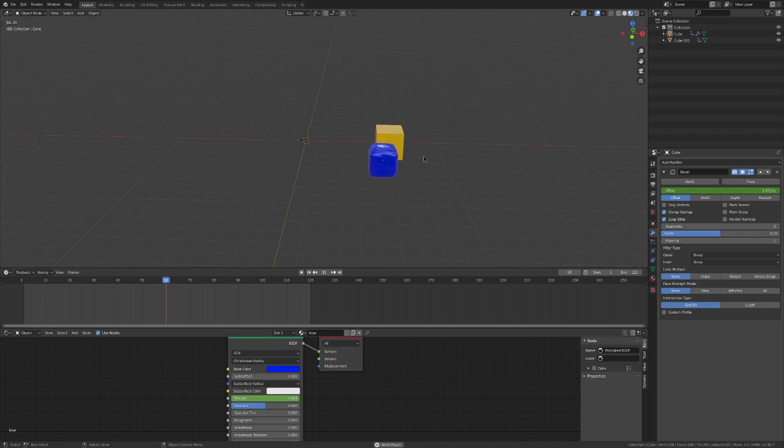So a huge scene, if you can, I would say that probably if it's the same environment, if it's not too big, I would just move the camera. But keep in mind that everything that is not in view, even if it's not rendered, is still in the memory. So when you are going to render whatever you're doing, you want to optimize for what's in the scene only, what's in view only. So in theory, yes, you can build a planet and then move the camera around, but then your computer needs to handle the planet while you only need to visualize a portion of it.